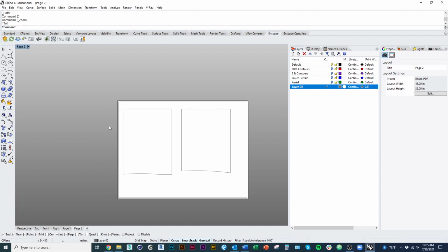And then essentially what you do is you print that out and you can temporarily lay the sheet by using tape or pins or any number of ways onto your material and just trace the outline of that material. You use your box cutter, your hot wire, whatever it is, trace the shape in order to cut out the material, and then you can remove the paper and stack them up. That's how you use Rhino to make a stacked topo model. All right, I will go ahead and end it there.